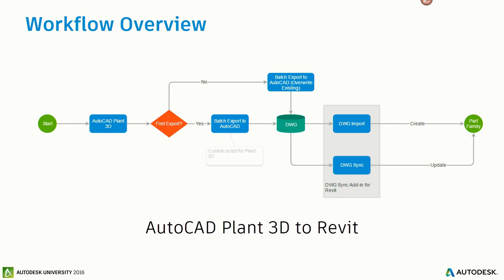Can you talk about the process if you have a structural engineer creating a separate model from the architectural model in Revit, and then you've got a mechanical contractor using Plant 3D, and go through the coordinate system of who should be talking? Yeah, that's kind of tricky. We've had several customers come to us with questions about coordinate systems in general. Keeping things lined up is really difficult if you don't determine a common coordinate system at the beginning of a project, because then everyone's trying to move their models around mid-project.